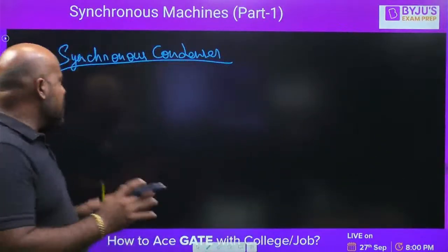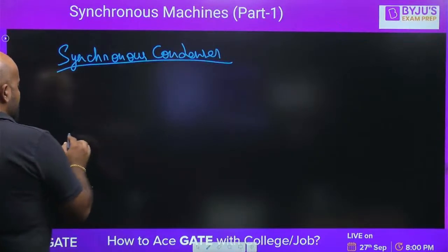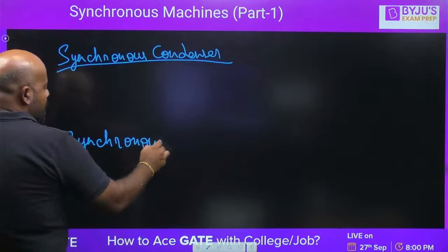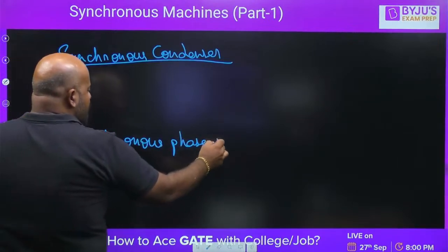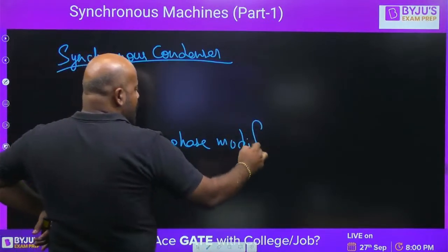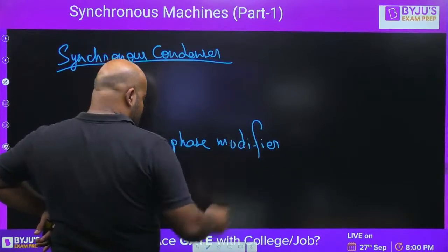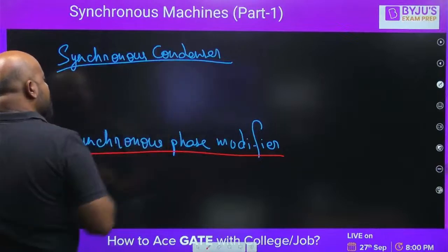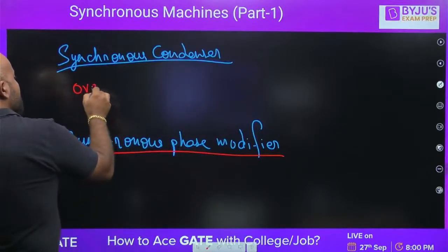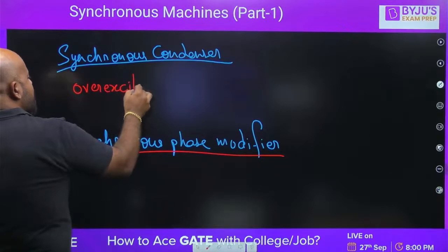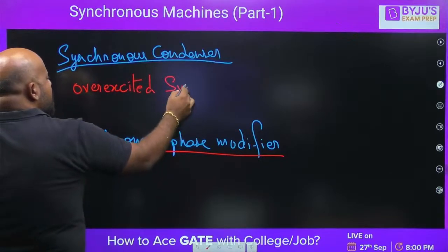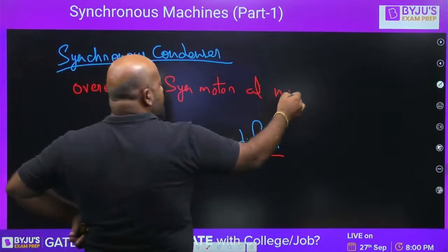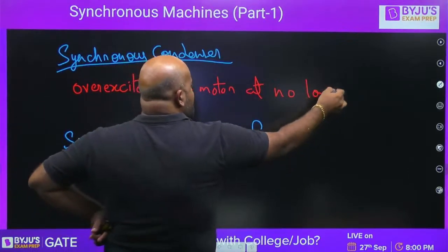What is the difference between a synchronous condenser and a synchronous phase modifier? You must have studied it in the power system, reactive power compensation. When you talk about the synchronous condenser, it is an overexcited synchronous motor at no load.